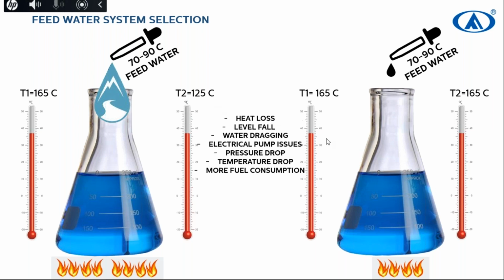And with proportional feed water, it will be like this. You will feed the boiler proportionally, step by step, and it will not cause pressure drops or temperature drops. The temperature will be the same and the pressure will be the same in the boiler room, and it will prevent water draggings into the system, and also prevent water hammers at system startup.